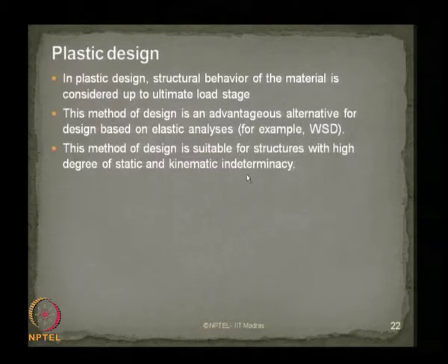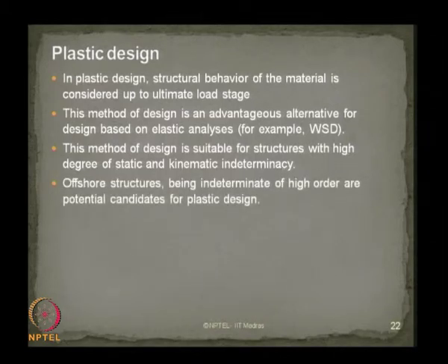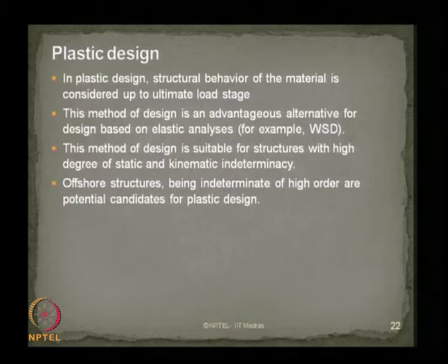The moment I say indeterminacy, it includes both kinematic and static indeterminacy. So, if you have an offshore platform with a very high degree of both static and kinematic indeterminacy, then one can go for plastic design as recommended for this type of structure. Offshore structures, being indeterminate of very high order, are potential candidates for plastic design.